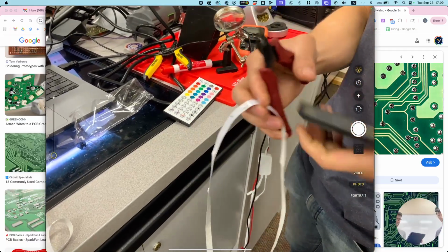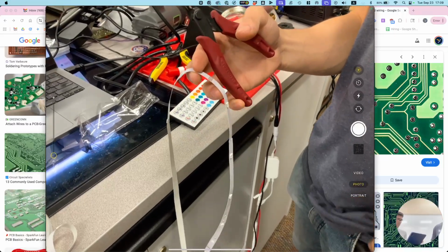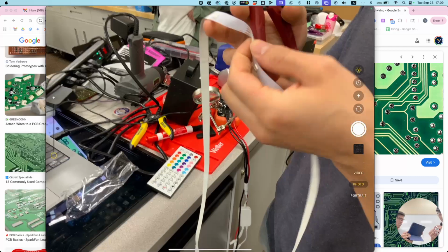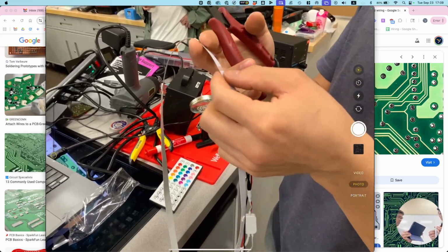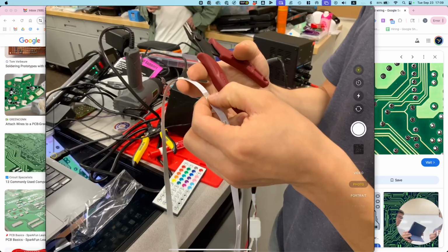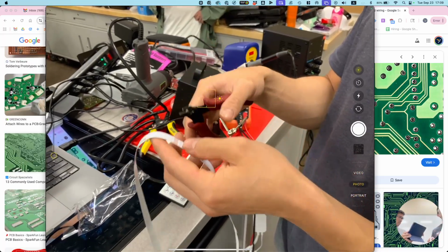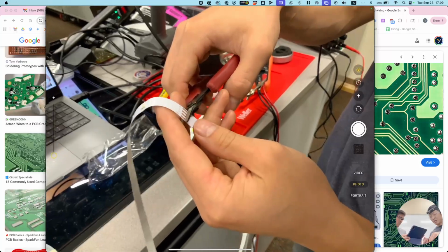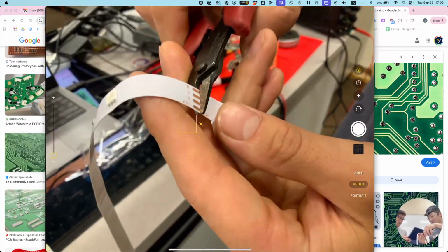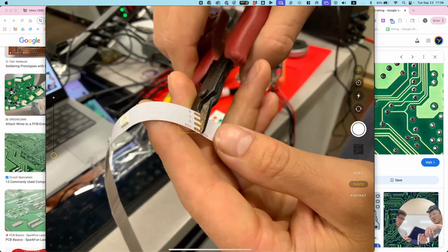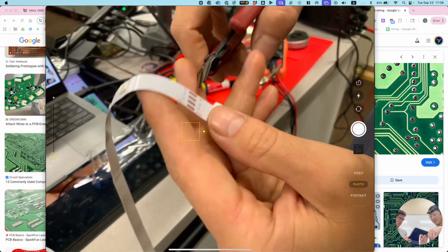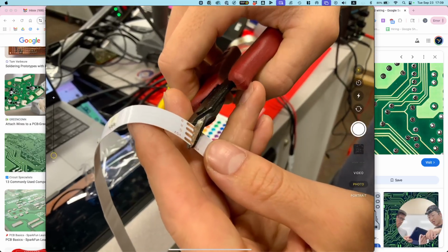I was doing LEDs, so there's connectors for this. Generally, you cut them on the pad. Okay, I was thinking of connecting later downstream, but yeah. We cut it on the pad, right? Cut it on the pad. Okay. I'm going to preserve as much of the pad as possible. So instead of cutting like this, because the portion that we're keeping is the top half, I'm just going to preserve as much of the pad as possible like this.